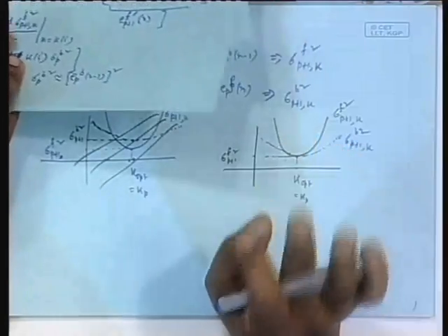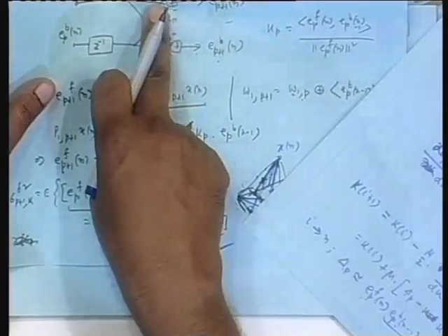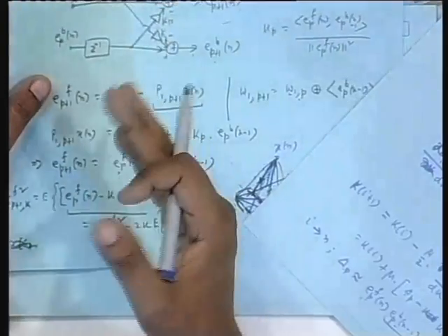But in the lattice I want them to be the same, isn't it? Because I know from theory that both the arms should have the same coefficient. That is not guaranteed in that separate business of LMS updating either the multiplier of this branch or the multiplier of this branch. How to get rid of that problem?